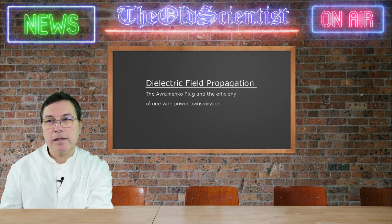Two diodes as a half bridge connected to one wire and to a capacitor on the opposite side, in parallel with a load. In my example, the load is the 18 watt fluorescent light bulb, 60 cm length. You might have seen experiments with LEDs or small xenon flash bulbs. I use a 12 volt battery and no ground connection. I also use 100 ohm on the positive battery polarity to reduce the maximum amount of power which can be delivered to between 1.7 and 1.8 watt.